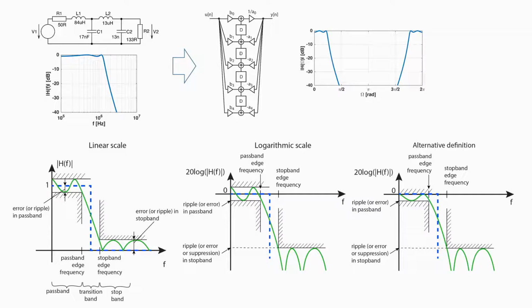Now let's take a look at how the discretization can be used to design discrete time IIR filters. At the beginning of the lecture, I told you that to design an IIR discrete filter, I can first design a continuous time filter with a desired frequency characteristic and then discretize this filter and turn it into a discrete time IIR filter that will keep that desired frequency characteristic.